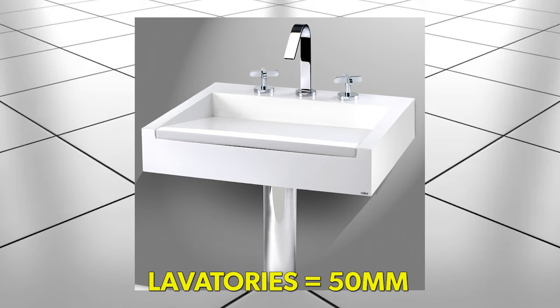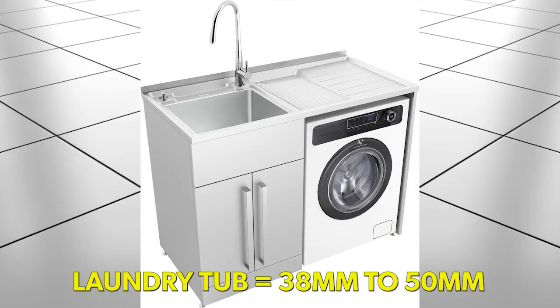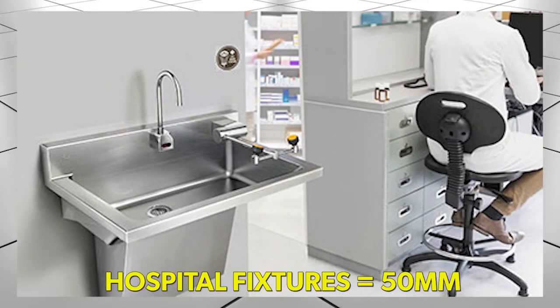Lavatories, 50mm. 8. Shower bath, 50mm. 9. Urinal, 50mm. 10. Laundry tub, 38 to 50mm. 11. Drinking fountain, 32mm. 12. Lavatory waste, 50mm. And 13. Hospital fixtures, 50mm.